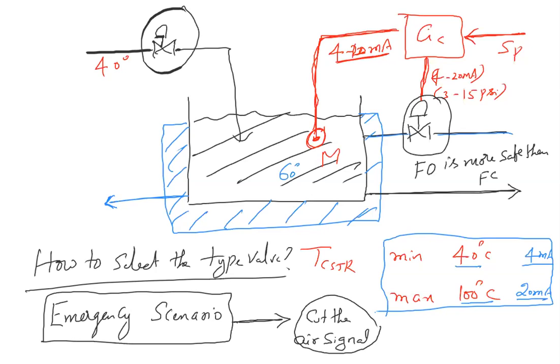So in an emergency, you should not think, I am wasting the cooling water, this kind of thing. In an emergency, safety of equipment is of utmost importance, because a small breakdown of the vessel will shut down the entire plant. Sometimes even small pumps will cause the plant to take a shutdown.